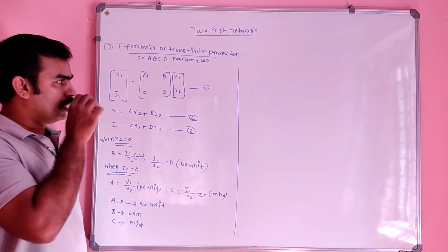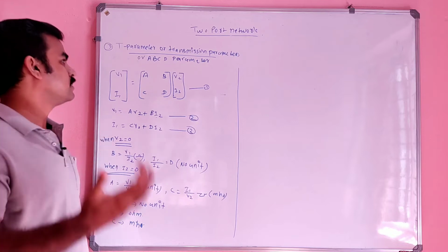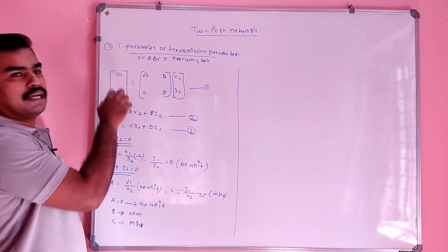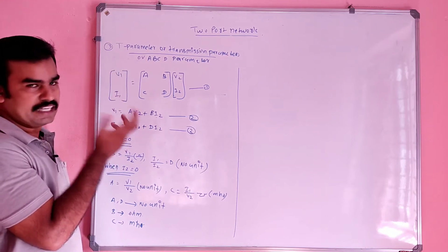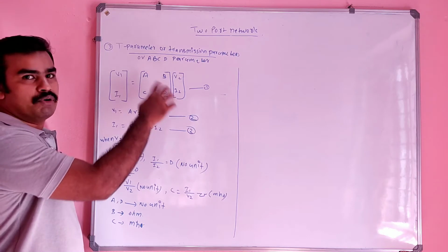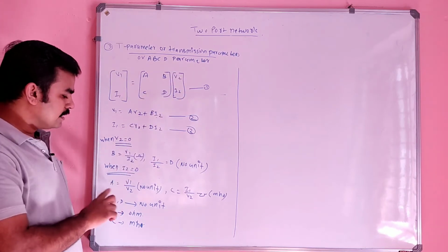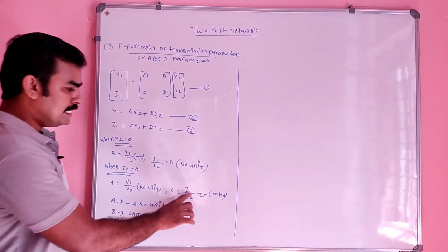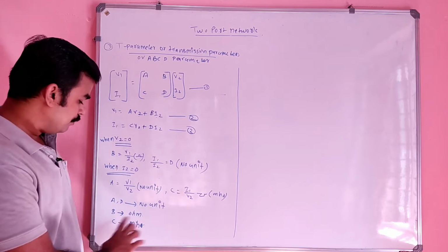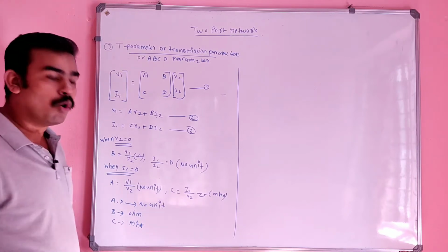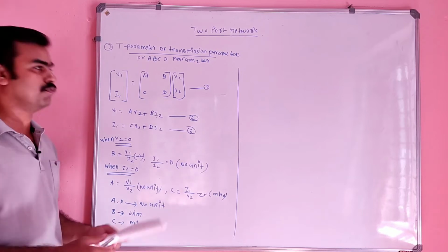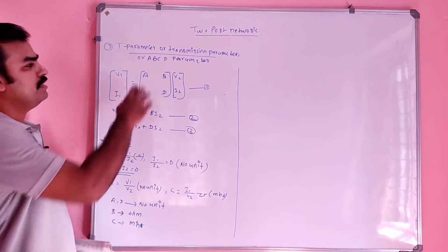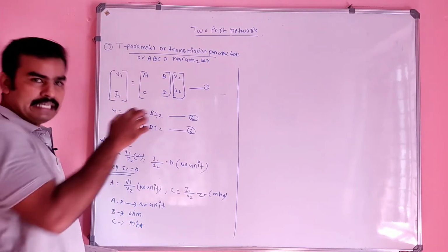Now for our circuit theory base, we just have to know what a transmission parameter is. Suppose some voltage and current V1 and I1. V1 is nothing but the input voltage, I1 is nothing but the input current. This is connected by this system or this equation. Then we learned that A is the ratio of input voltage to output voltage, no unit, and C is I1 by I2. A and D have no unit, B is in ohm, and C is in mho, or ohm raised to -1.